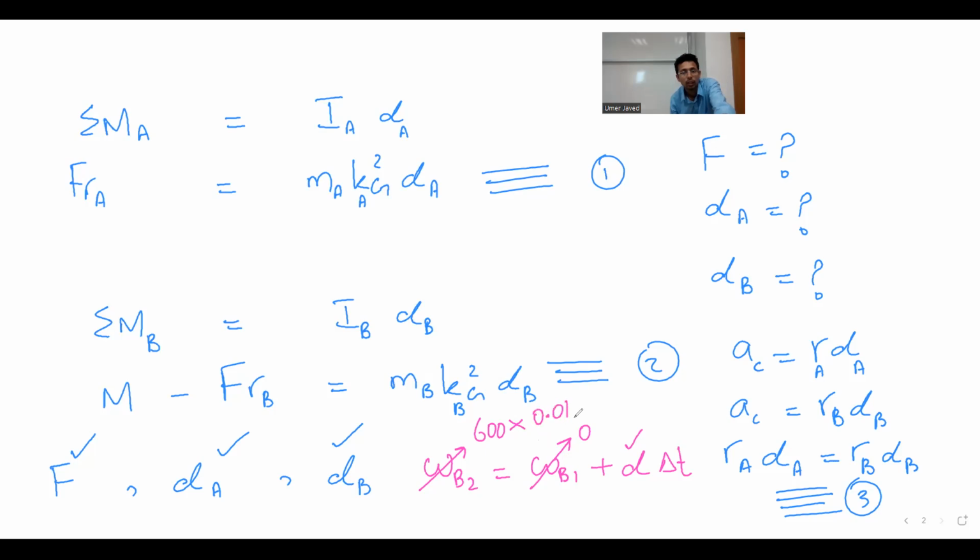The entire thing, when you multiply and convert. Just give me the conversion, RPM to radians per second. Rotation per minute: 2 pi times, divided by 60, not 660, because it's per minute. Okay, so we have this, and alpha is known, and you can find delta t.